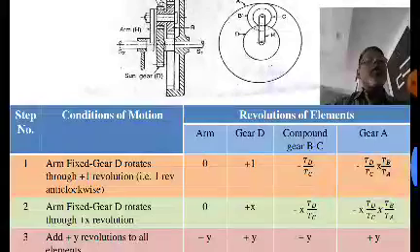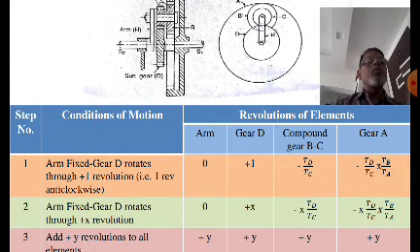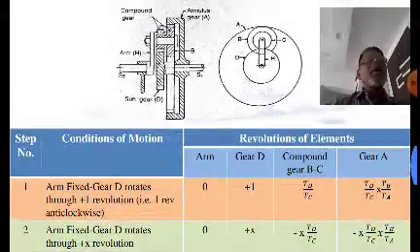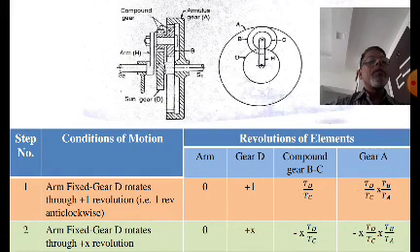So I have taken the gear D rotating through one complete revolution, right? This D is the innermost gear, correct? So plus one revolution we have taken. Now the gear D meshes with the gear C, correct? So how can we write it? TD divided by TC.